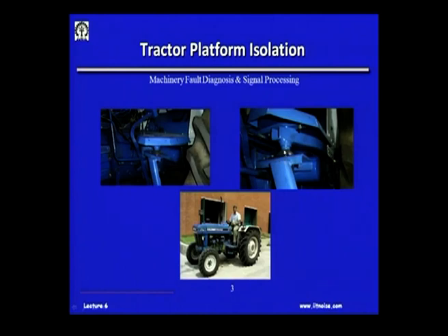The mechanical power flow is reduced by having a structural impedance mismatch, which is created by this vibration isolator. So, depending on the payload being subjected to the isolator, depending on its mass and the frequency of operations, I can decide on the natural frequency of the oscillator and the stiffness characteristics of this isolator. This is another such view of these isolators, and they need not be elastomer or polymeric mounts. They could also be spring mounts, because elastic mounts wear out with time.